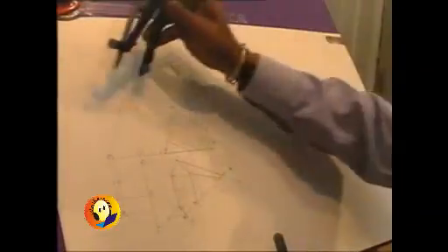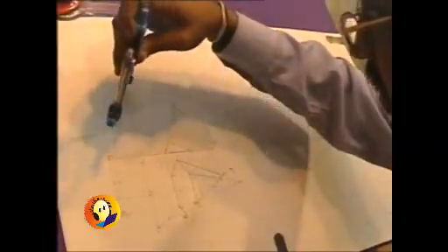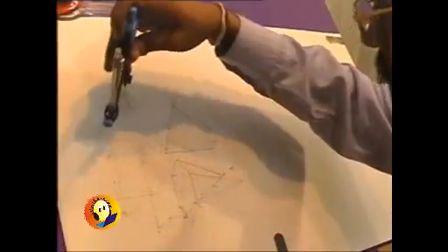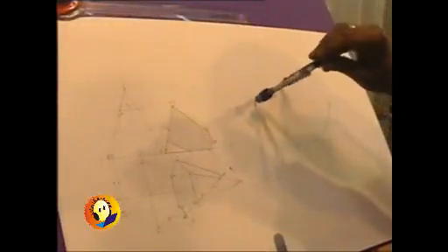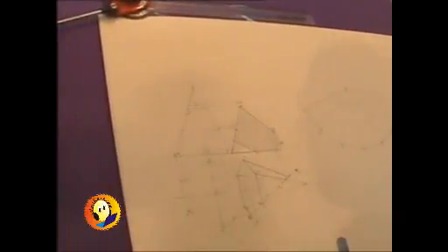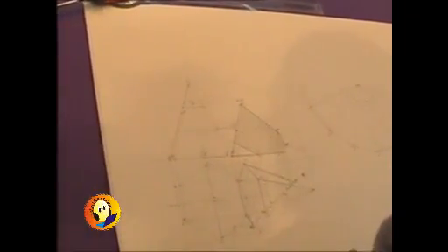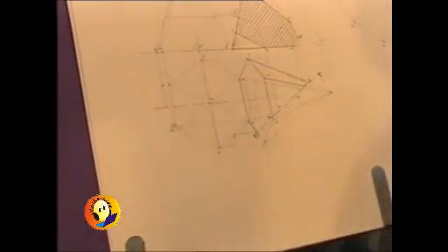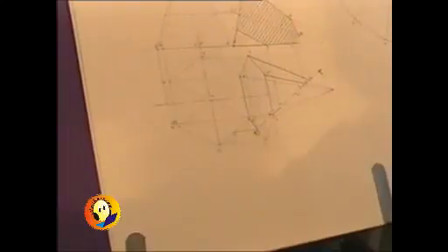Earlier I had said that we should not be drawing arcs in case of the pyramid problems, but here as all the points belong to the generators, even the arc technique can be used. So I have marked all the points over there. Now the question remains about the points which are to be marked explicitly, and those points are namely point number 1 and 2.